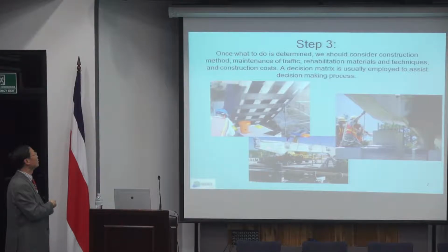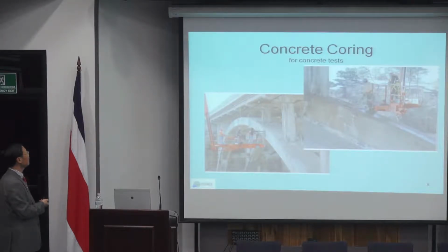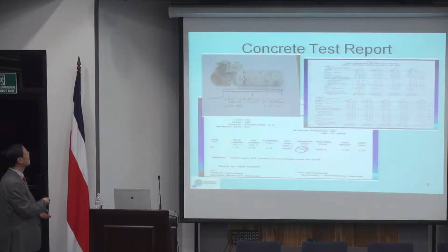That's the original they took off, and that's the new one, to speed up the construction. And that's during construction. Of course, they removed all the deteriorated concrete, and then patched the concrete. They didn't use regular concrete, they used shotcrete. Shotcrete is much faster. And after that, they just used FRP.